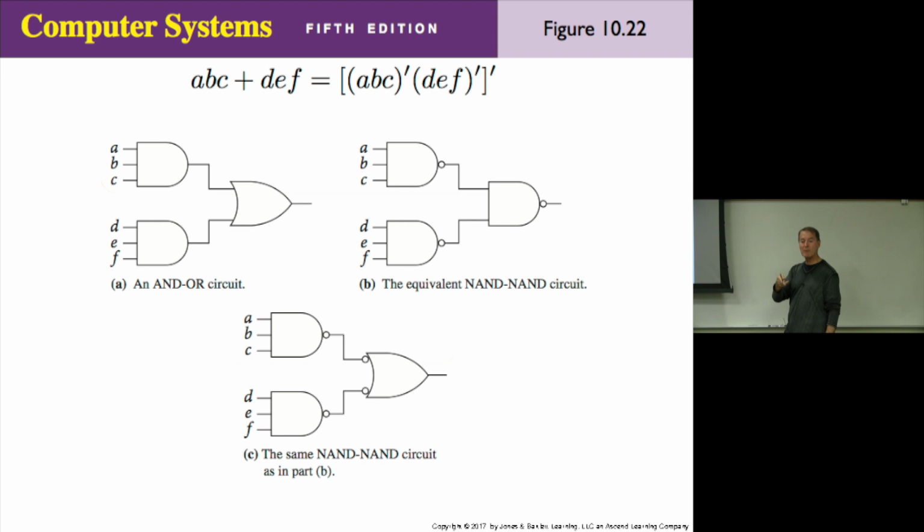Remember in the lab we had the quad 2-input 7400? Yeah, exactly, you could do it with one chip. Good point, like in the lab. All right? So because of this mathematical relationship, it's just a mechanical thing. If you have a two-level AND OR, you just draw them with all NANDs.